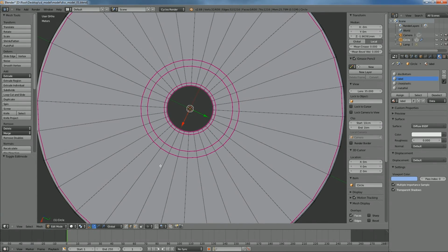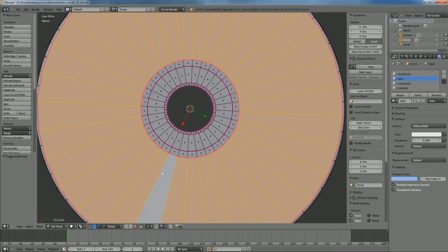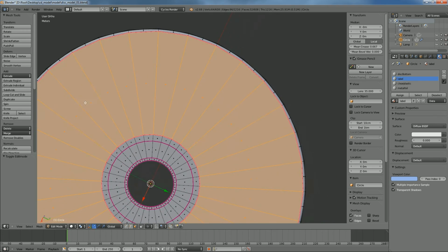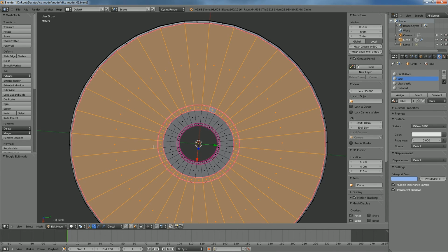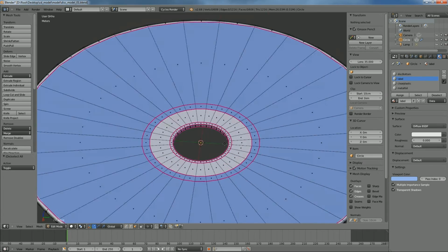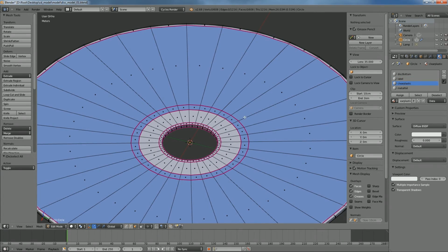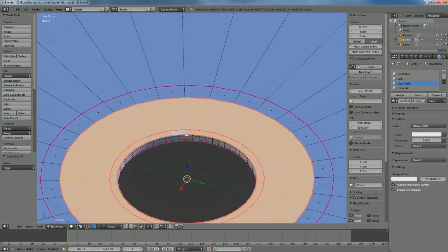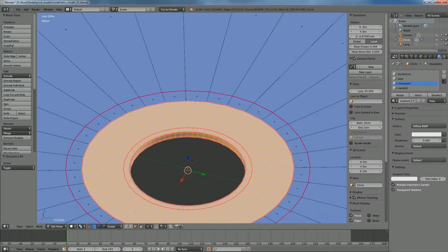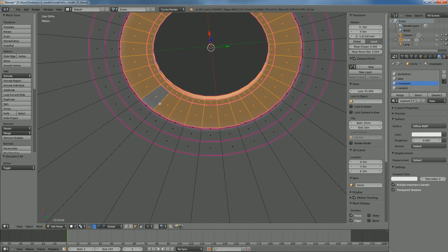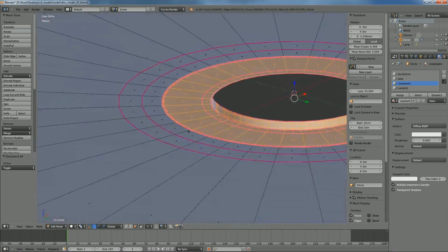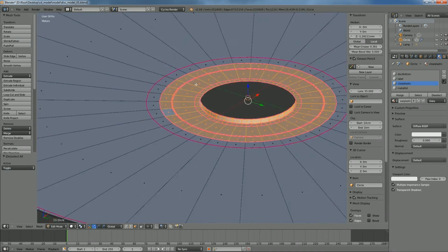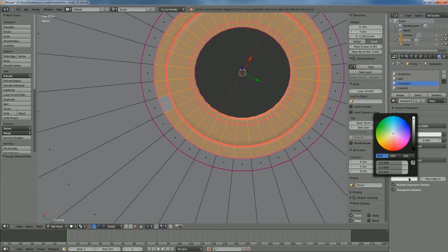If we go ahead and look, we can select all of these faces here. We'll leave the outside edge for a metal, because they don't print right to the edge. They do have a bleed. So we'll have these faces here. That will be the label, so we'll assign that. So now you can see we have a label. Clear plastic will be all of this inner stuff. And then the same on the bottom. And that goes right till there. So that'll be clear plastic. Assign that. We'll give that a white color in the viewport.